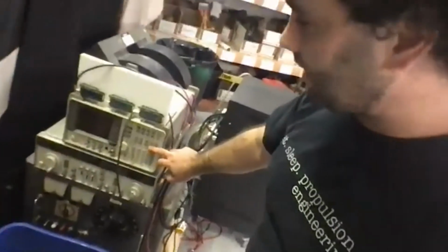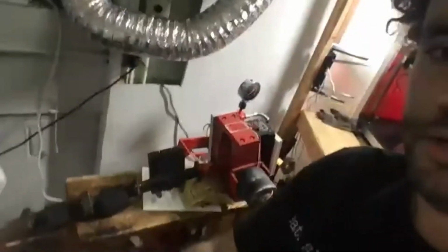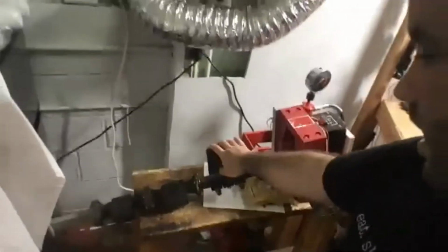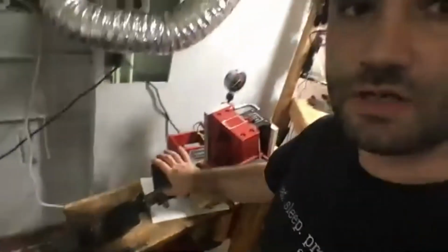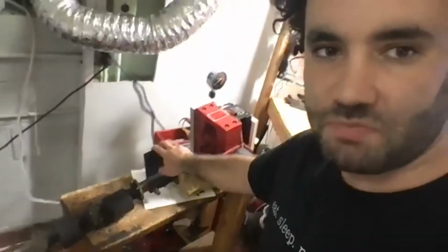That's a signal analyzer. Down there is a 5,000 volt power supply, which is going to be powering this klystron over here. It's a C-band klystron. And it goes to a cross guide. This is going to tell us when the chamber at the end is in tune, and then there are some isolators to keep all the power going in one way.